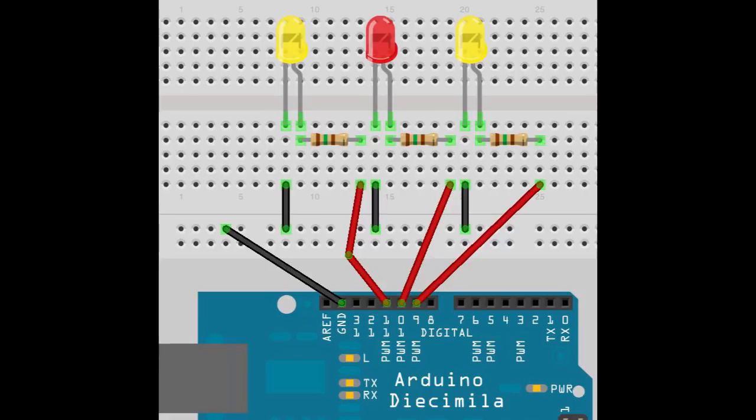Now, if you're not familiar with how breadboards are set up, first I want you to notice that there are two horizontal lines of sockets that are kind of separated from the rest of the breadboard at the very bottom. These are typically used to connect your positive and negative sides of your circuit, and the sockets are connected together horizontally all across the length of those horizontal lines. On a breadboard, typically these are marked positive and negative. There's a space then with no sockets, and then you see a set of 5 horizontal lines of sockets, and then a gray line, and then 5 more horizontal rows of sockets. These two sets of 5 rows of sockets are your working area on your breadboard.